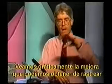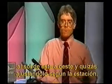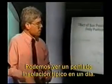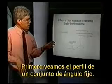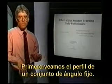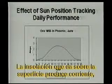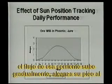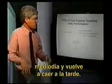Let's take a look graphically at the enhancement that we might get from tracking the sun east to west and perhaps adjusting seasonally. We can look at a typical insolation profile in a day. First, let's look at the profile from a fixed angled array. The insolation falling on the surface produces current. That current flow rises gradually, peaks in the middle of the day, and falls back down in the afternoon.